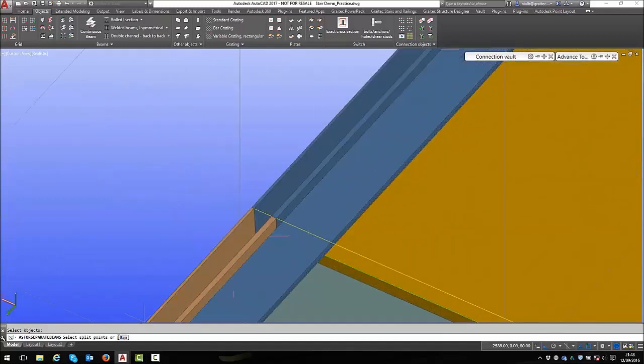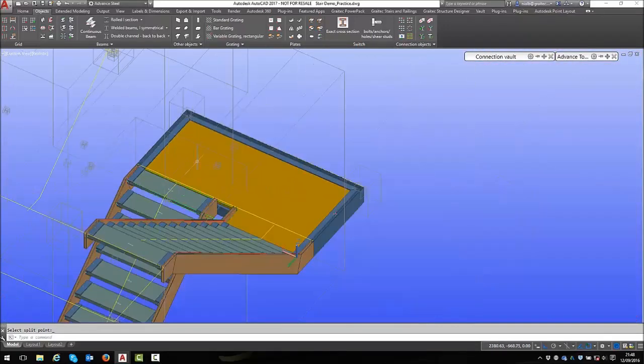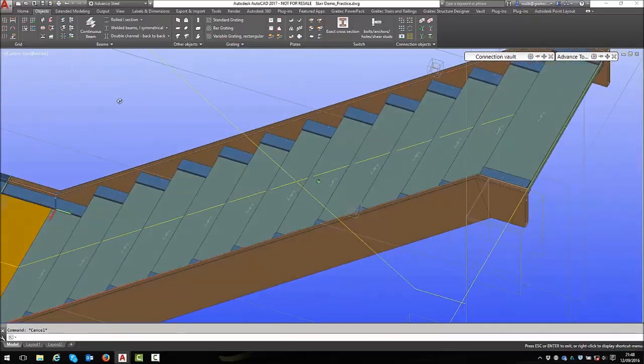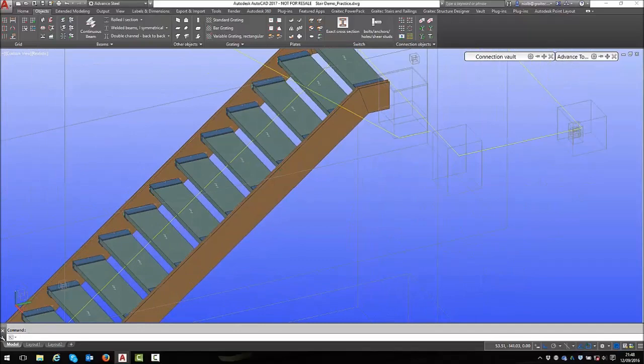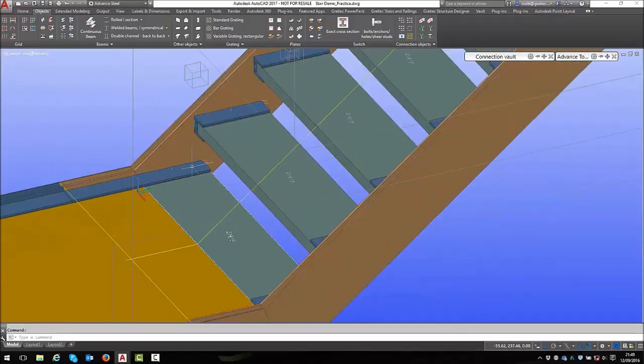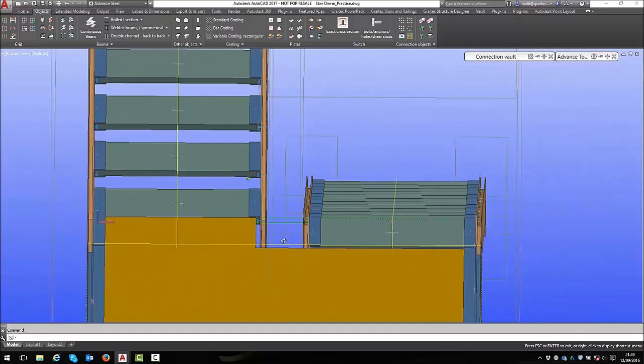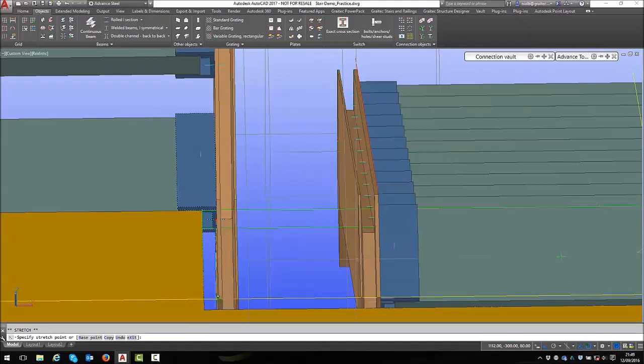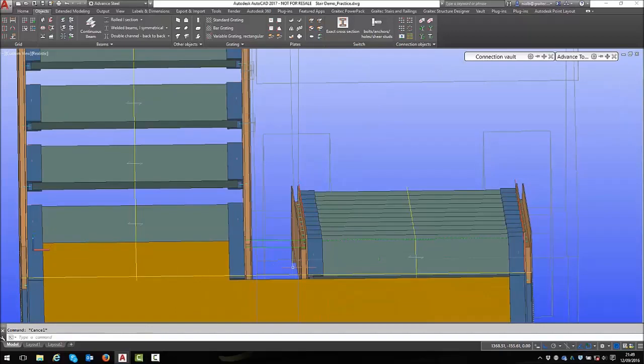The only other thing I need to do, I'm going to split this. And notice when I split this, I can put a gap. So I'm going to also leave a 2mm gap there. And I'm going to split it at this point. So there it is, split. And again, I'm going to split this one at this point, 2mm gap. That's it. Okay. Let me just extend this through. I'm going to extend that to this endpoint here, 300. Okay. So that's done.